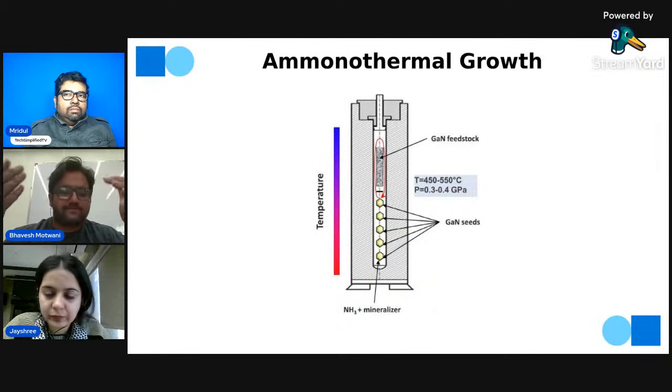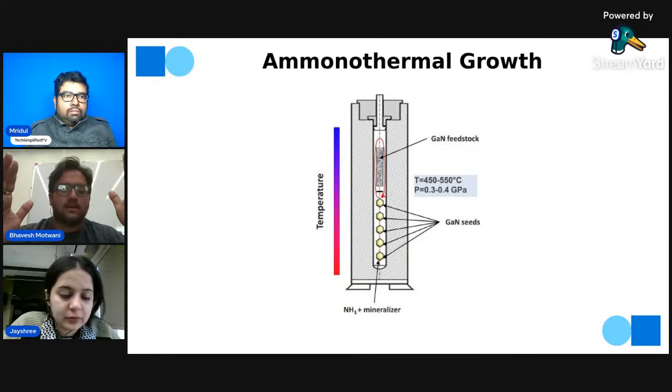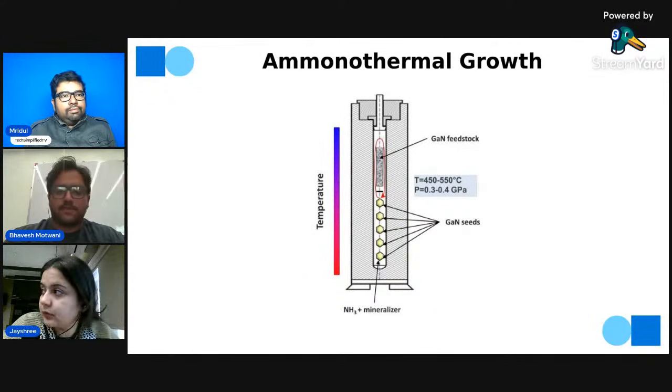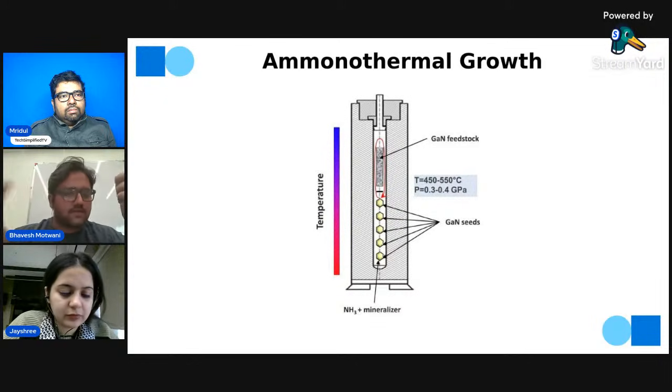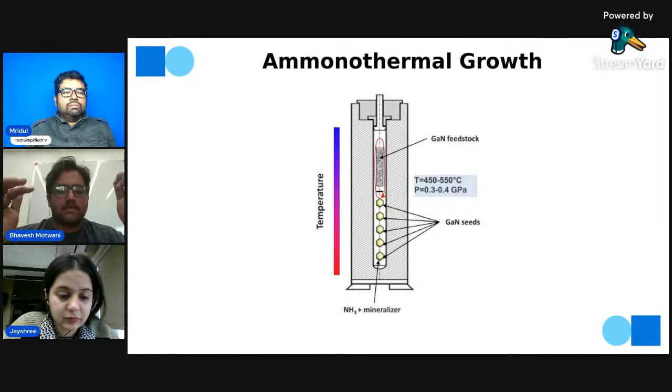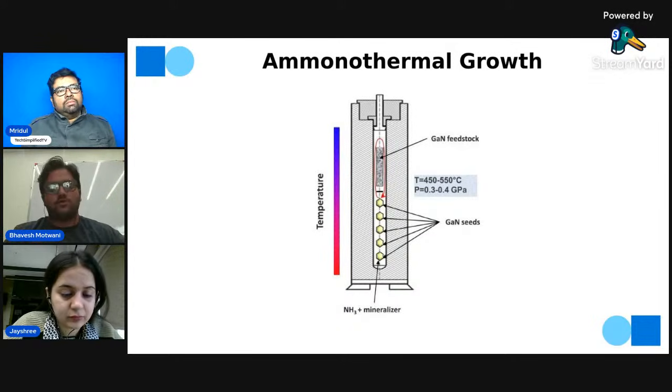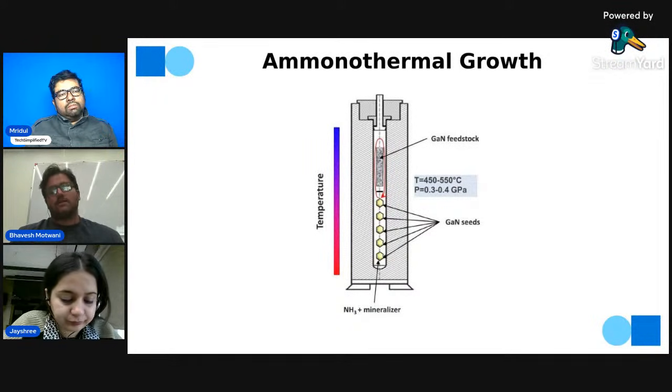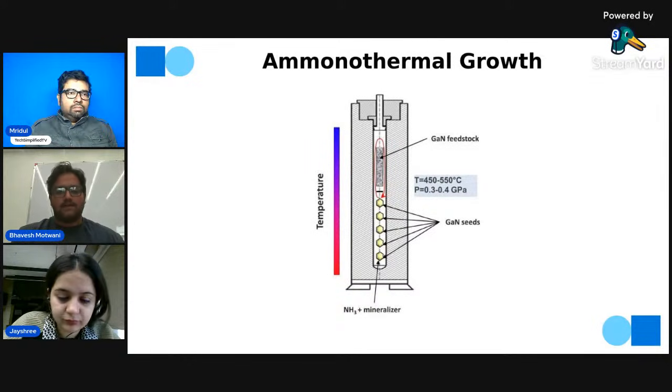Then we come to the Bridgman growth. Bridgman is used for gallium nitride and indium phosphide compound semiconductors. Czochralski is used for sapphire wafers. Then the top seed solution introduces the seed and the solution mixed all together to make a wafer at a low temperature and with proper pressure. And with that, we get ammonothermal growth also, which is expensive, but it gives exceptionally good yield and exceptionally good wafers compared to the other compound semiconductor growth techniques.